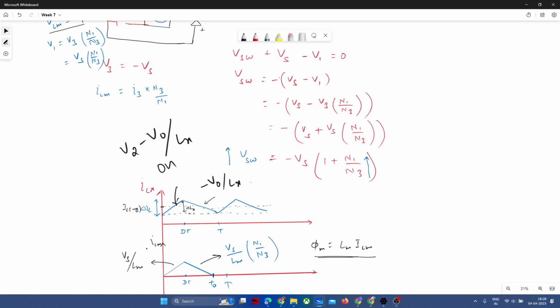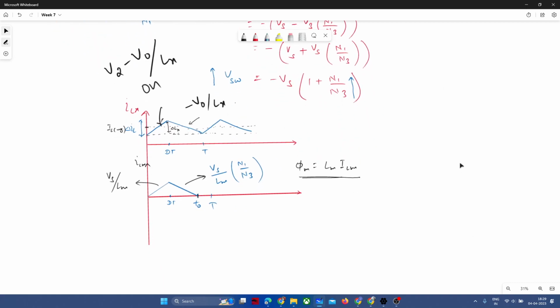Okay, so this inductor Lx that is connected towards the load side might be in continuous conduction mode or in discontinuous conduction mode, but the inductor which is the magnetizing inductor must be in discontinuous conduction mode. So this ILM or this LM must operate in discontinuous conduction mode. Why am I saying this LM must conduct in DCM? Do you have any idea of this?